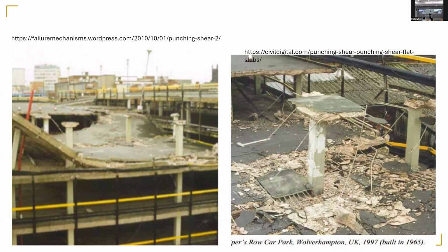So now that is part of the design requirement, that you should provide enough reinforcement at the bottom of the slab on each column in each direction to carry the entire weight of the slab by hanging, so it doesn't fall down. It may break, but it should still not fall down and crash the slab below.